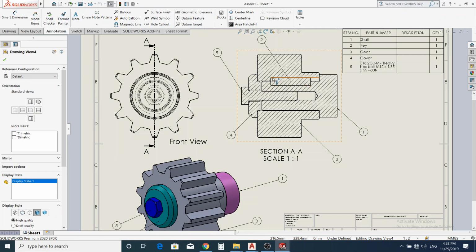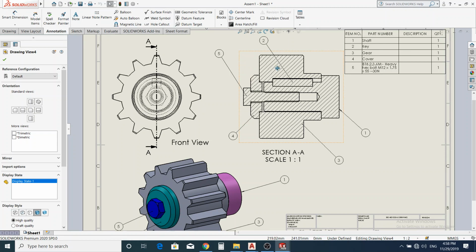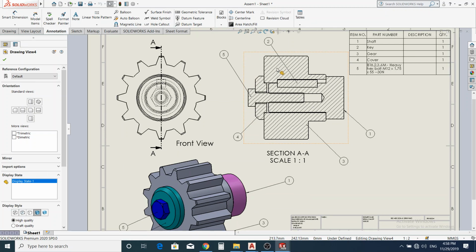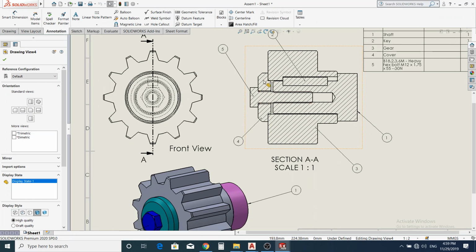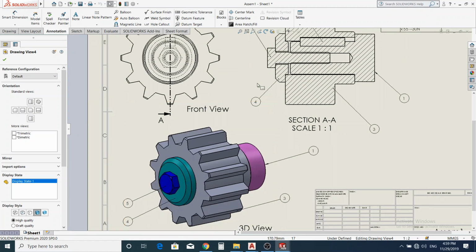After doing that, I needed to restrict the translational movement of this spare gear in this direction. Remember, we have already restricted its translational movement in the other direction by stepping down the diameter of the shaft at this end. So I will be using this cover right here.